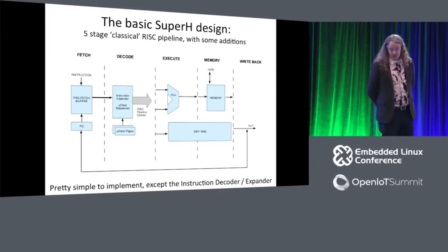In this particular case, we modified three instructions to take one extra clock cycle because they wrote back 2 things to the register file. And everything else is writing 1 thing to the register file. And it's just a question of making sure that you get all the pipeline hazards right. And that gets done in the microcode. So when you look at this for SH2 versus J2, there's 1 or 2 extra clocks in a few of the instructions as a result of doing that. But it drastically simplifies the logic of the processor. And it makes it practical to implement.